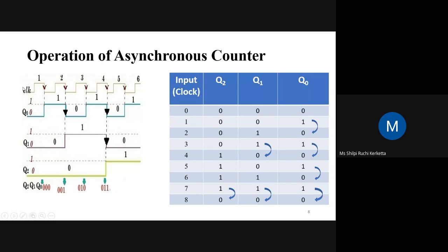So this 3-bit counter is negative edge triggered. At first we are giving 0, 0, 0. So everything is 0, 0, 0. So we can say the JK flip flop is working here, where we have used negative edge triggering. Whenever we get a 0, or this falling edge, it will change, because in JK for 1 1 it is changing to the opposite.